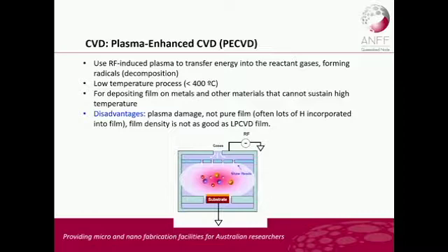The advantage of the process is that it is a low temperature process. Once you have metal on your substrate or device, it doesn't allow you to go to high temperature like the LPCVD process. So you need to use the PECVD process to deposit a layer like a passivation layer on your metal.